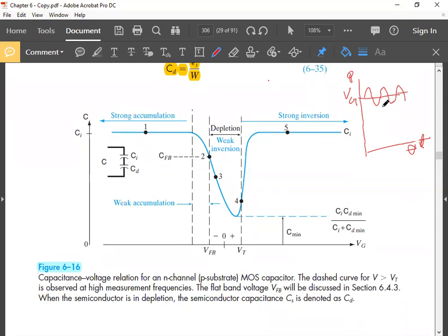They have to go to the p-type material, recombine, or be generated in the p-type material, then come to the inversion layer. These things take time. So for a high frequency AC signal used for capacitance measurement, the inversion layer will no longer contribute to the capacitance. So the capacitance CD will be fixed at that minimum value, which was there at the strong inversion point.